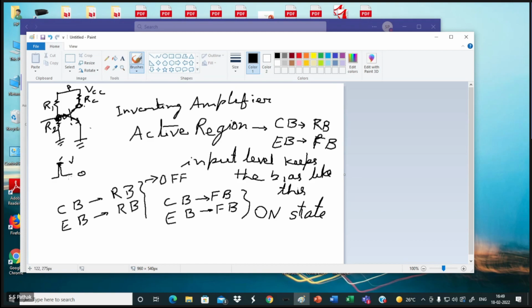So this pulse applied takes it to the on state, and removing it takes it to the off state. This pulse will be coming from my circuit now, which will control the switch, taking the switch into the on state or off state. The circuit is generating this control voltage V that is operating this inverting amplifier. Now it is biased like that. So what is the initial bias?